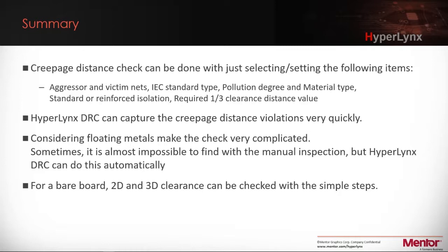Consider the floating metals in your design and how complicated this process can be. We're talking about validating a circuit layer by layer, net by net. You have to consider these safety checks, the clearance and creepage checks. This can take hours, days, or even weeks. So HyperLynx DRC can do this automatically for you, and you can find these in a matter of minutes. And so it makes it very easy to find and correct these safety issues that your PCB can have.